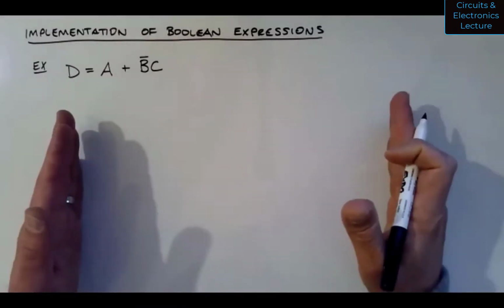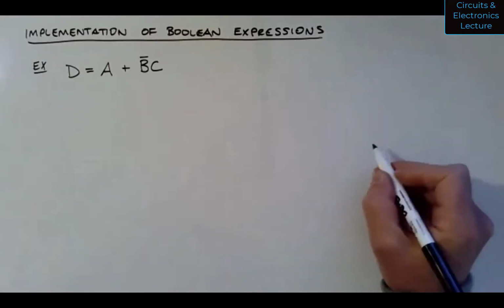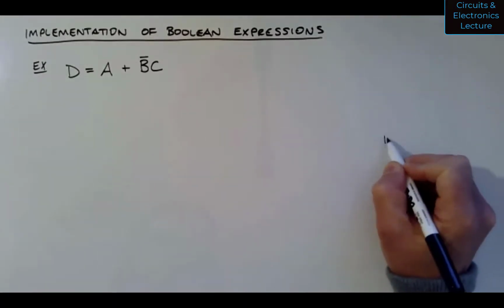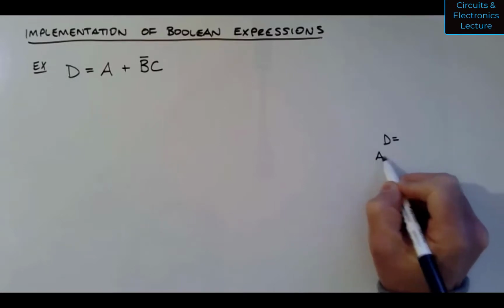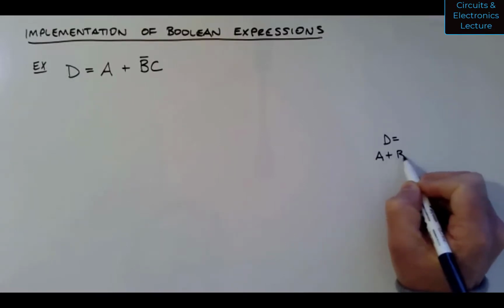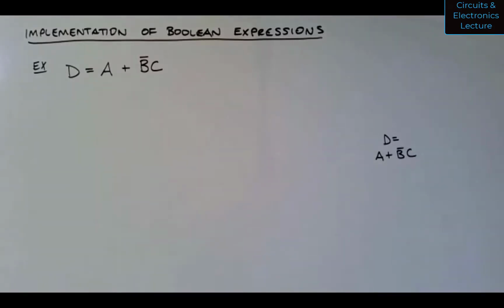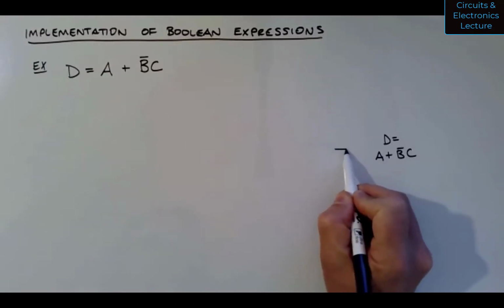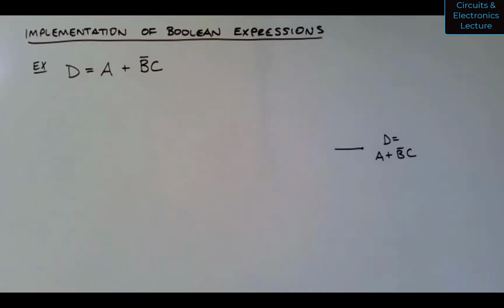So I'm going to have a circuit here with gates, and on the right side at the output, I want D equals A ORed with the inverse of B ANDed with C. Yes, you can take words that are normally conjunctions in this class and make them verbs, kind of like texting, a noun into a verb. So I'm going to start at the output. This is a wire at the output, and perform the last logical operation or Boolean operation that I want to perform.